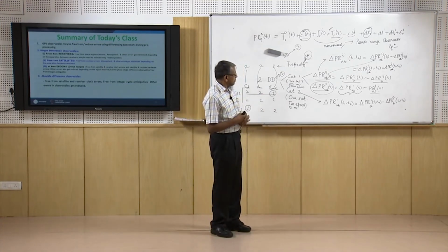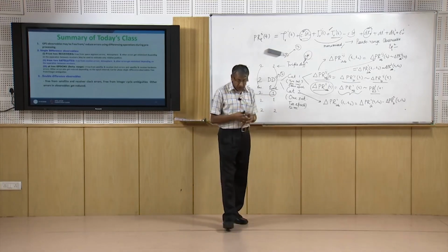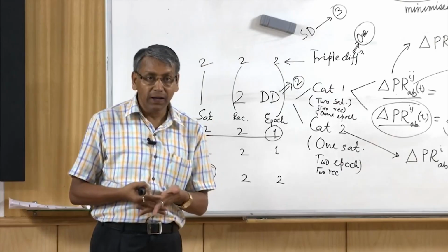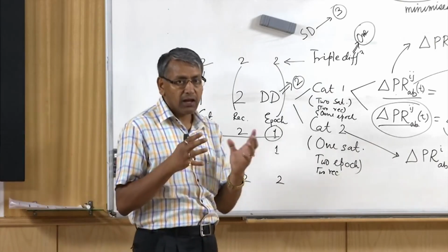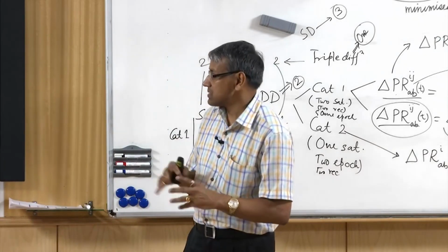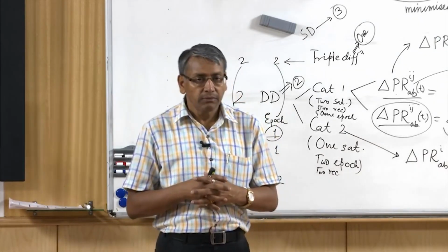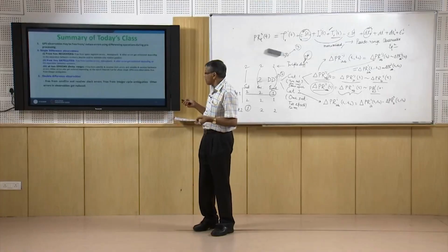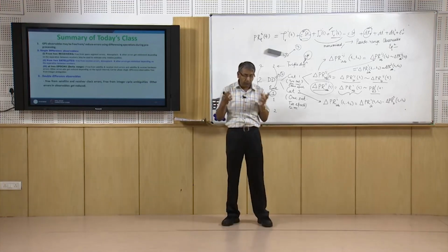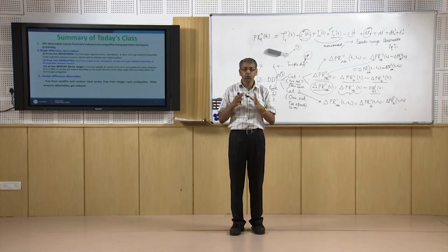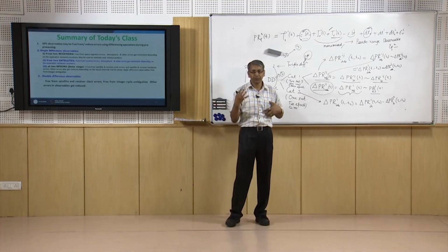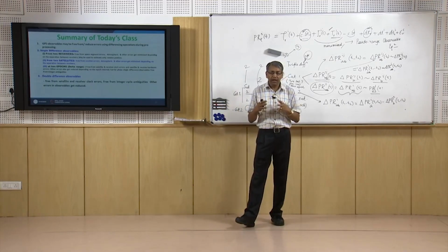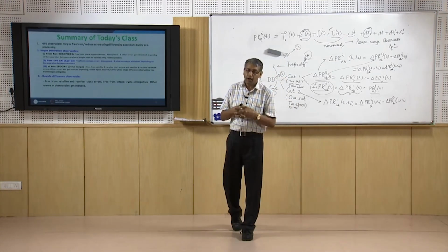However, these double difference observables also contain the error due to multipath and also the noise, as well as the atmospheric errors that cause some erratic behavior. So, we need to further process it, and however double difference observables are the best observables which we should go for processing for precise positioning, after finding out the approximate position by making use of triple difference observables.